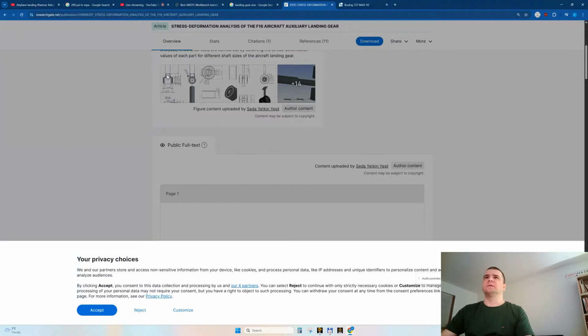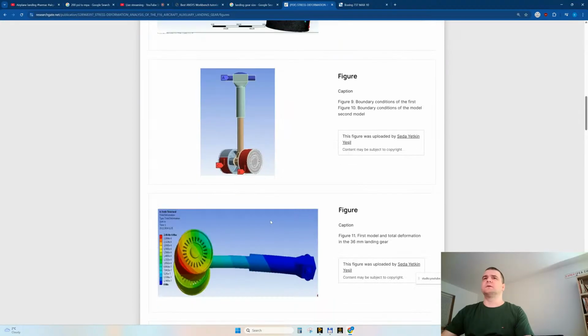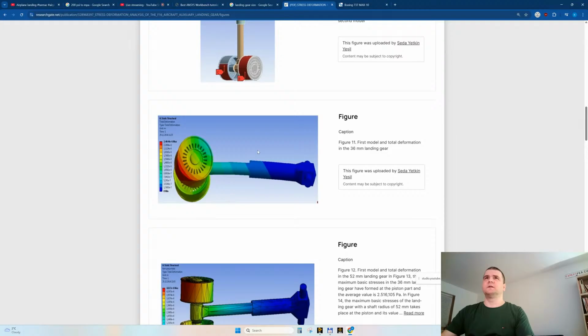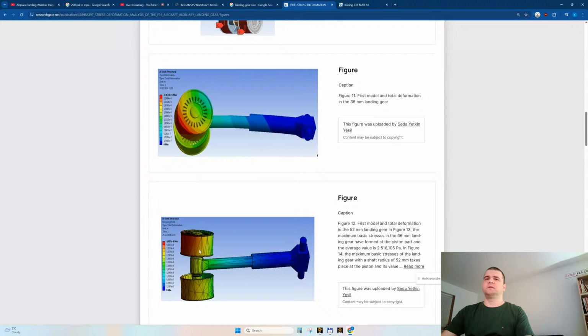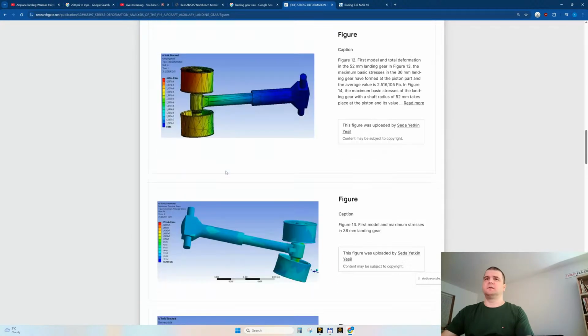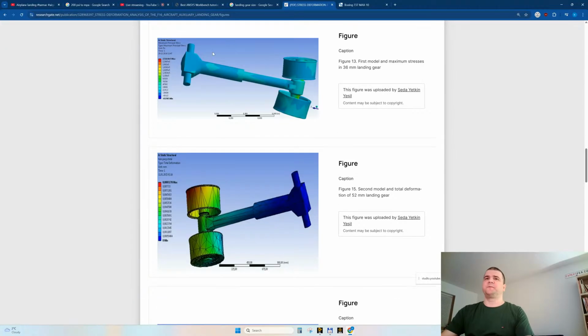So, for example, this shaft, what? Okay. This shaft, oh, he has done some FEA in ANSYS workbench. Perfect. He has only a compression of this shaft, this inner shaft inside. But as coarse as it looks like, and it looks horribly coarse, I think, yeah, there is no translation. Everything is bonded. We can clearly see that it's bonded.